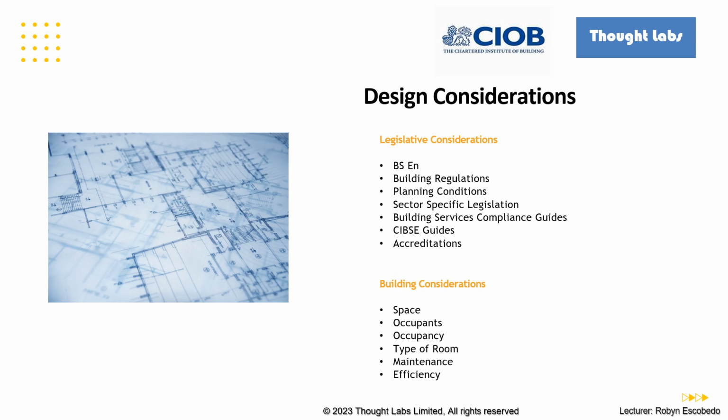Maintenance of the system will also be required periodically. Consideration should be taken into how this would be undertaken and the likely disruption. For example, if the full building is provided for by a ground source heat pump and this has a problem, then the full building would be without heating or hot water. Whereas, say, there was a modular boiler installation and there were 4 boilers, even if one of those boilers developed a fault, there would still be 75% of the system running. Therefore, the building would still have some form of heating and hot water. This resilience is an important design consideration.